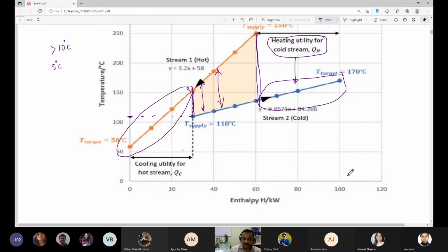So many kilowatt. And then per kg of steam, how many kilojoules does it provide? Because if the steam condenses, it provides you the heat. And then if you run it for a year, obviously you have to leave out some shutdown period. So if you run it for a year, how much steam you require, and then there is a price associated with it. I have some price by US standard, and I believe it is a few rupees per kg, say 2 rupees per kg.